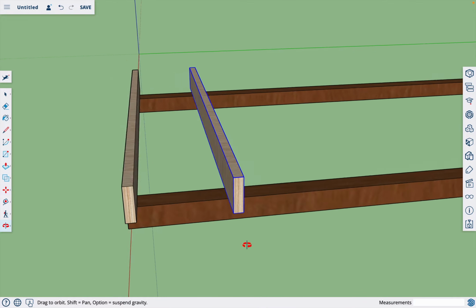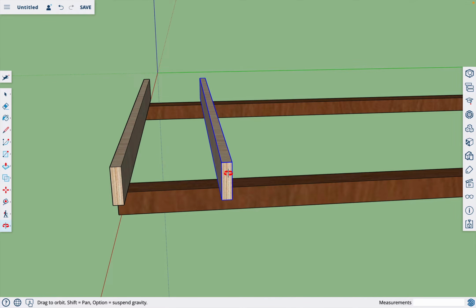And the reason is all the boards from this point forward are measured from center to center, 16 inches, but the first board is measured from the end, so that your sheet goods, like 4x8 sheets of plywood, will fit on the end here and then end up on the center. So if I measure from here to center, type in 16, enter, it's dead centered here. So that's why we move the first board 15 1/4.